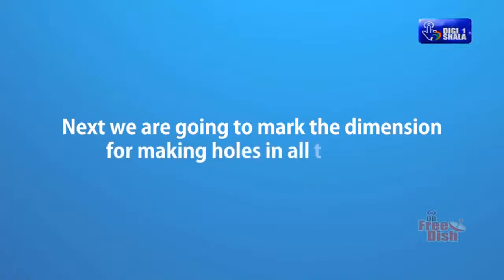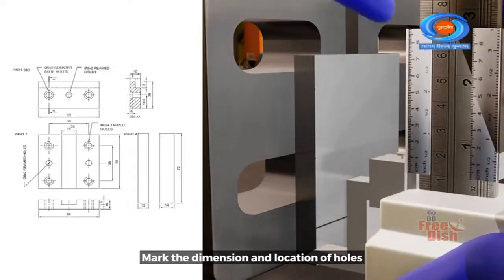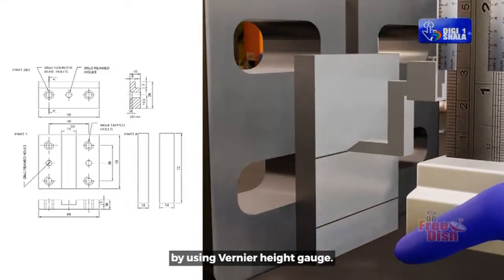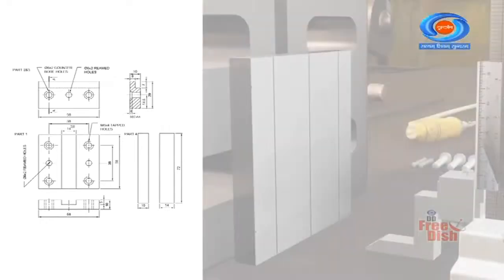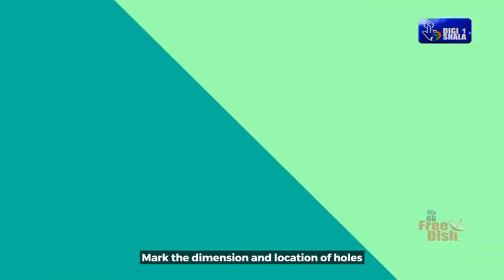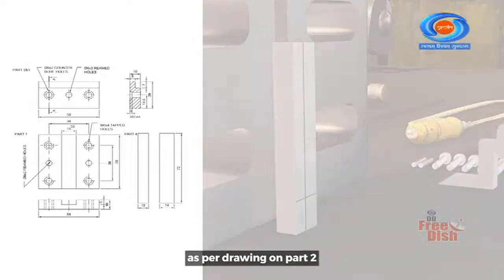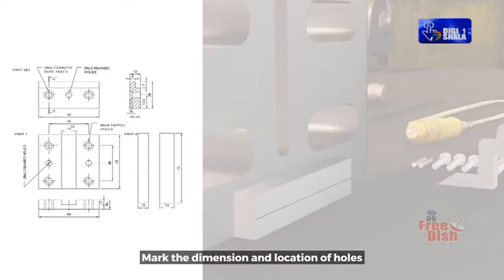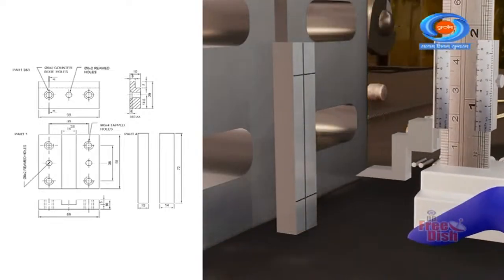Next, we are going to mark the dimension for making holes in all the parts. Mark the dimension and location of holes as per drawing on part 1 by using vernier height gauge. Mark the dimension and location of holes as per drawing on part 2 by using vernier height gauge. Mark the dimension and location of holes as per drawing on part 3 by using vernier height gauge.